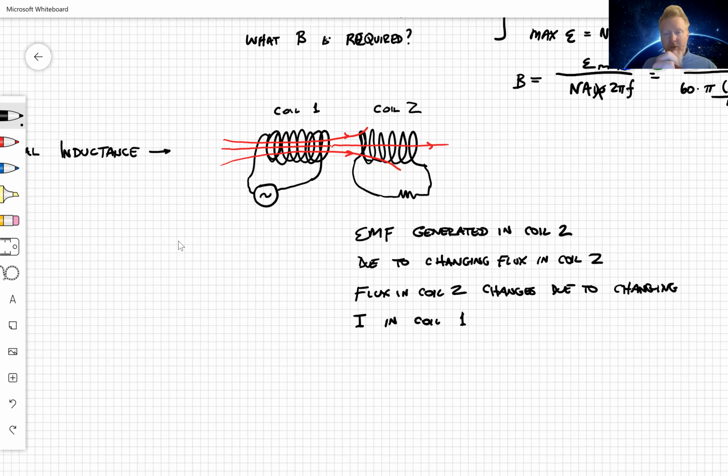He started by putting a coil with a current in it next to a coil with just a voltmeter or a current meter, and found that, oh yeah, look, I can make the needle wiggle because I'm turning this on and off. Okay. So that's wireless power transmission, right? This is known as mutual inductance because I have one coil inducing something in the next coil.